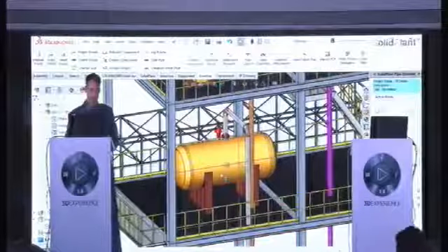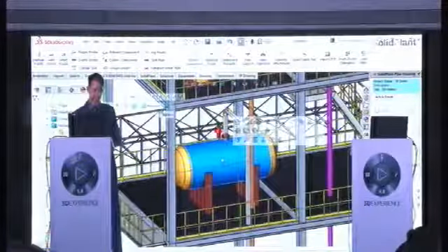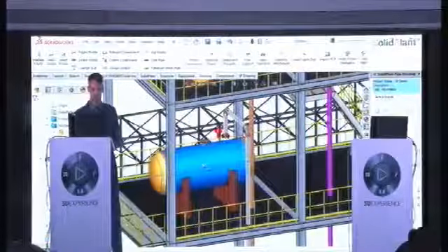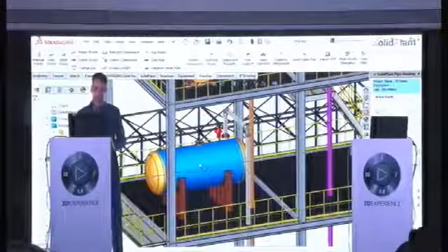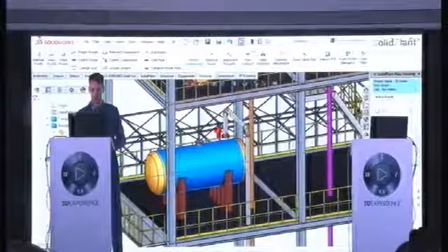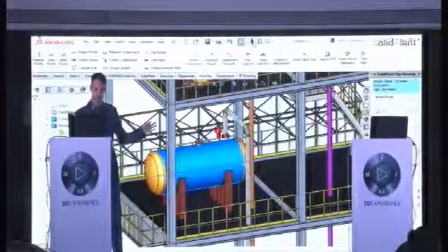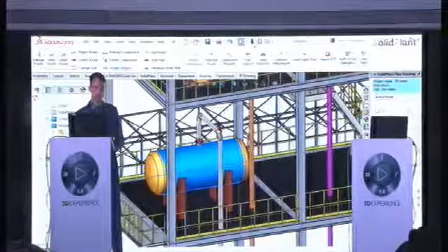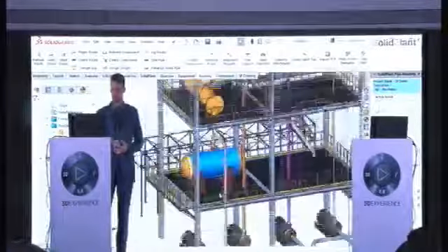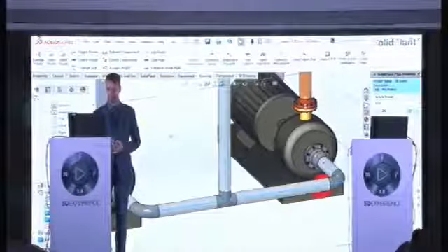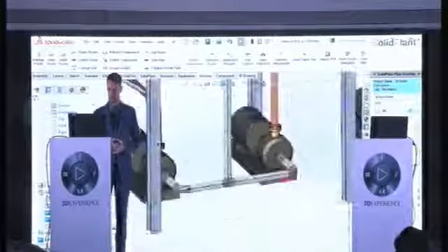In another solution, when you want to move something, it might get detached from your equipment and you have to draw the whole line again, which is not what we want to do. So we can simply move this equipment and rebuild the position of our line, and it will get reattached to it without any loss of data. So there you go.